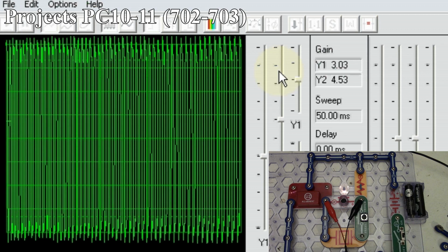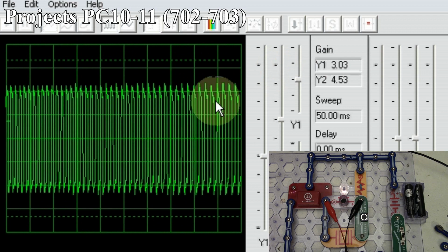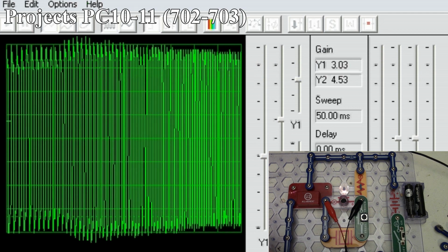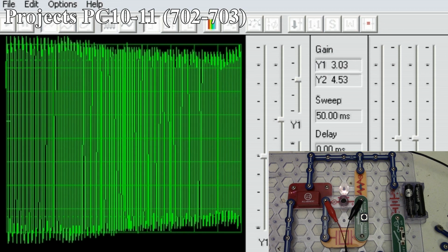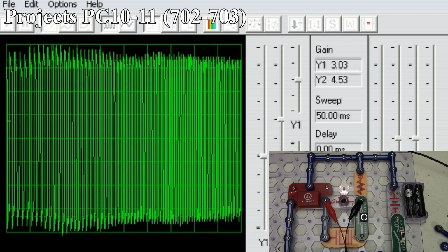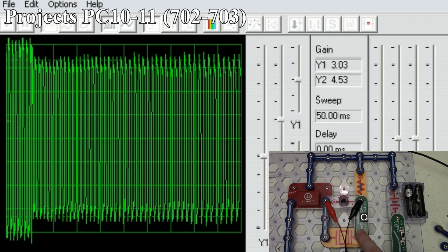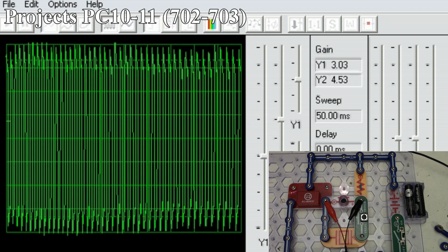And you see when you look at our waveform here, you see that it's got peaks. Now I do have to mention here, you see my hand, I'm going to put it on the laptop and then take it away. And you see how that waveform is changing? This is one of the things, again, you have to keep in mind. And I put my left hand on the laptop and it's doing the same thing. You have to be aware that you can influence interference on the circuit.